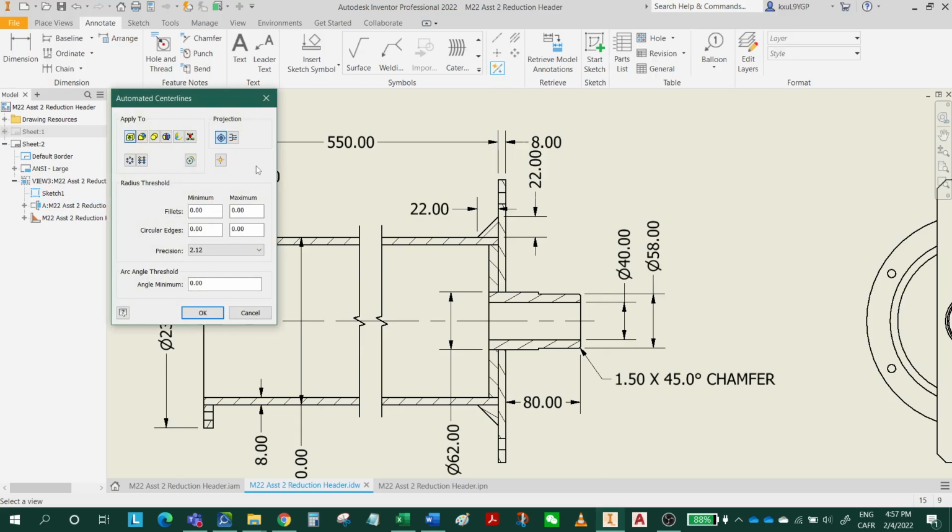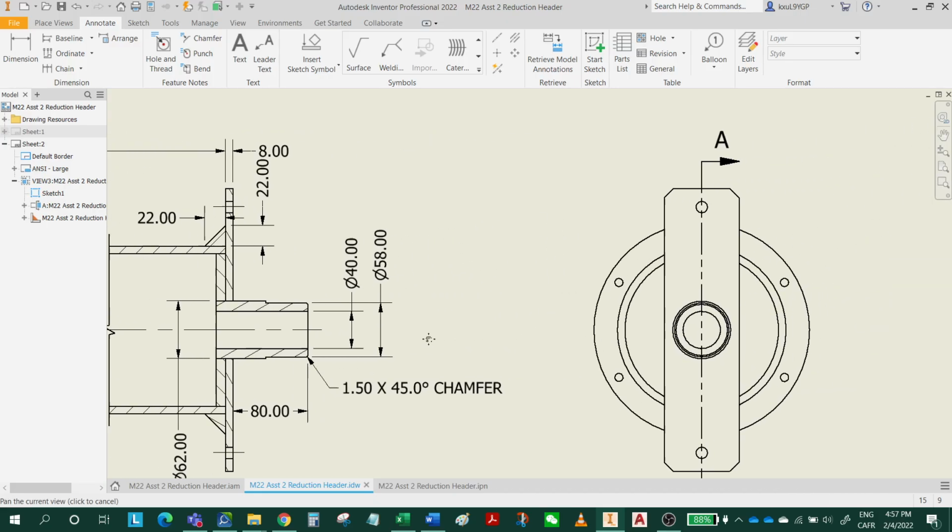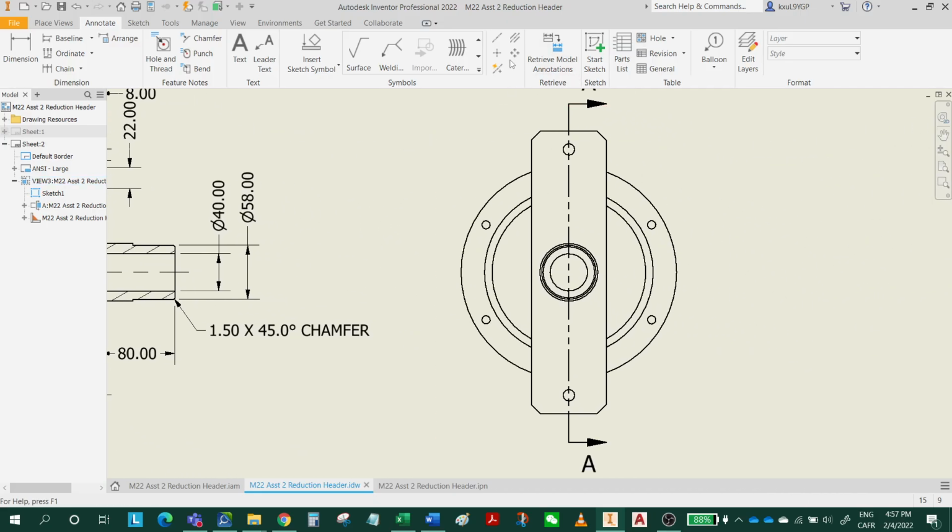Click the view, and I'm going to add a center line here for this view. See, for the object in view axis parallel. Click OK. So you see it automatically adds the center lines for the holes. All right. Next, I'm going to add the center mark for this circular pattern of holes. So I'm going to select this one first and select this one. I don't see that one, but I have this one. Right click, create.